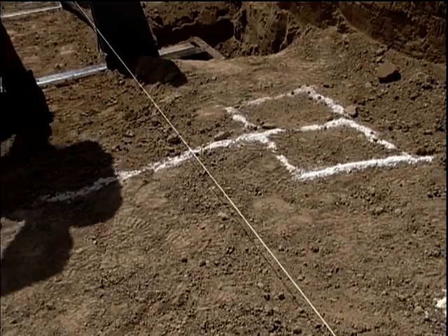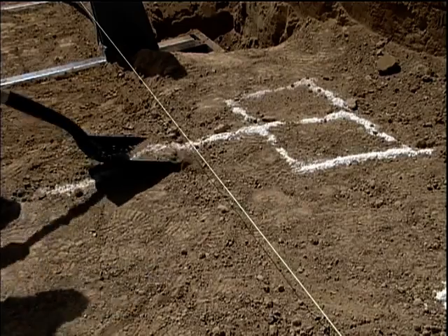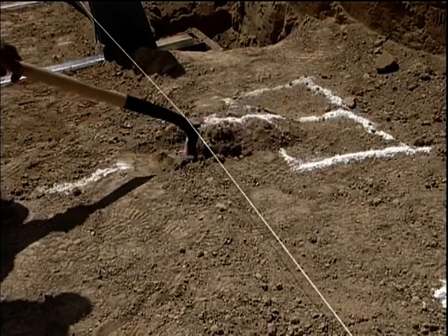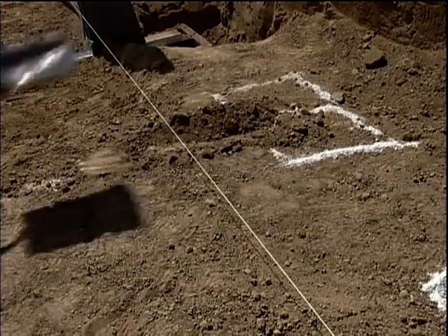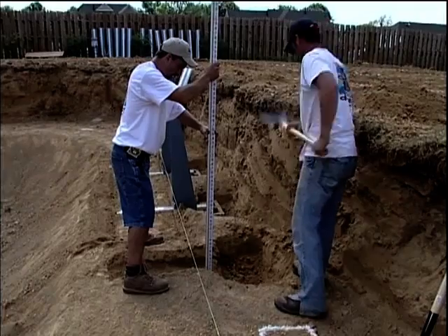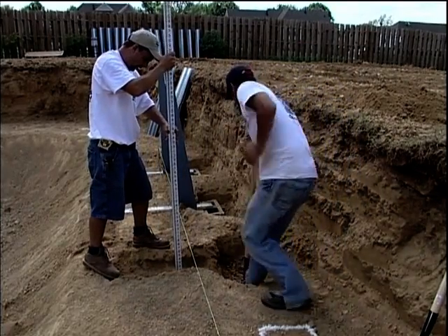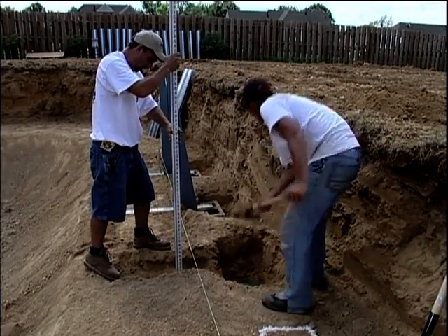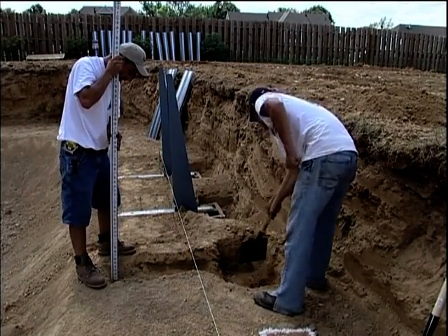First, you dig an 8" wide by 16" long by 11.5" deep block hole, and a long trench for the ground supports, measuring 4 inches wide by 36 3/4 inches by 3.5 inches deep from the block hole. This is where you will install the concrete blocks. The holes should be dug to have the bottom of the block hole to be 11.5 inches from the level of the pool floor. Check this excavation with your transit.